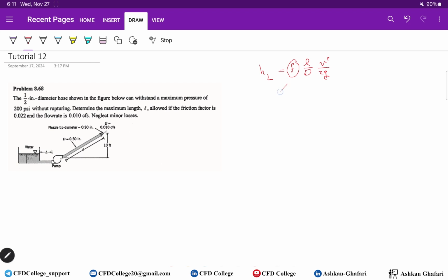As you know, in laminar flow it's equal to 64 over Reynolds number, but in turbulent flow you have some equations. They are not explicit, they are implicit equations. It's hard to work with them, it's difficult to use them. You can't do it on paper, you need an advanced calculator. The second way is to use the Moody Chart. So it's important for you to learn how to work with this Moody Chart.